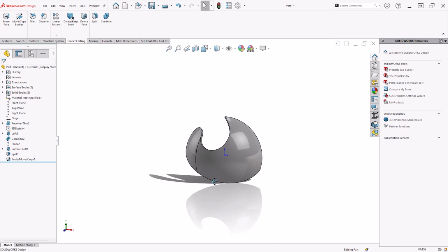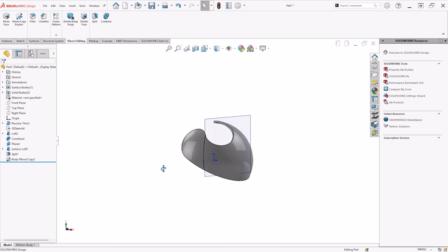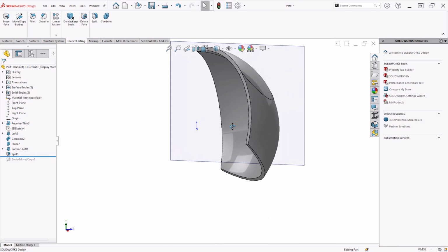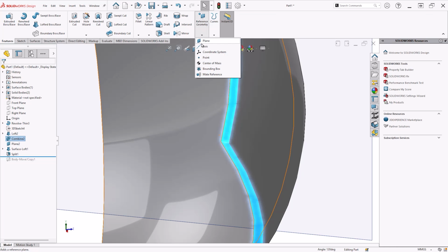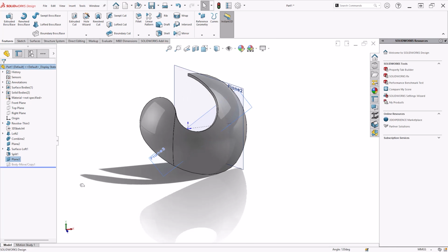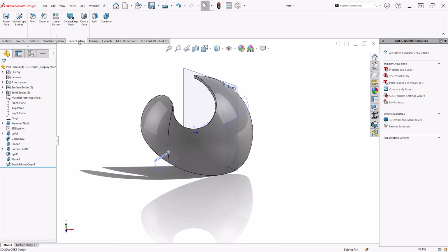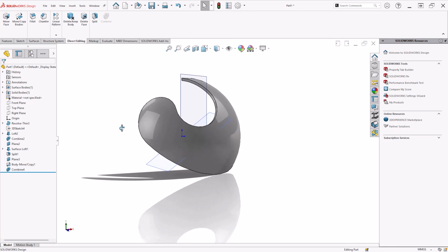However, I don't want to necessarily do that because I think I can make use of this plane here, and I can probably create another plane. So let's just keep the body where it was. I'm going to create another plane using these two faces, another plane like so. And again we're going to move this thing back. We're going to use the combine command again, so direct editing. So combine these two, we'll add them together. There is no common geometry between them, so add them together.